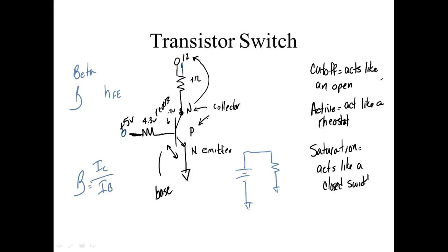Huh? They say none. Kirchhoff's law says the sum of the voltage drops in a closed circuit has to equal the applied voltage. So whatever voltage was on this battery would be dropped across that resistor. What if it's 12 volts? Well, that resistor would drop 12 volts. What if it's 30 volts? Well, that resistor would drop 30 volts. So if I wanted to get a voltage out besides the applied voltage, I'm going to have to set up a voltage divider, right? You understand?